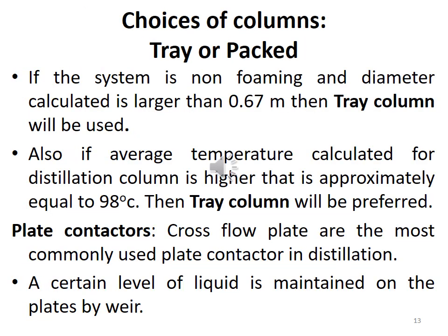Okay, if you are using the non-foaming system and the diameter of the column is greater than 0.67 meter, then tray column will be utilized. And if the average temperature calculated for the distillation column is higher than or equal to 98 degrees Celsius, then tray column will be preferred.